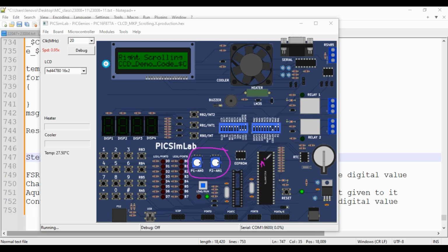So this microcontroller comes with a built-in ADC block, and this ADC block should convert the analog output provided by this pot to a digital value. So we are going to configure this peripheral, which is nothing but the potentiometer.